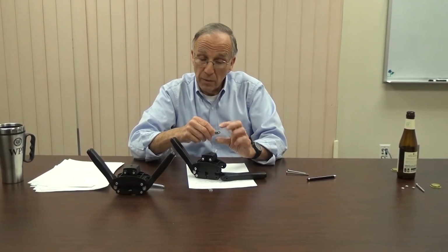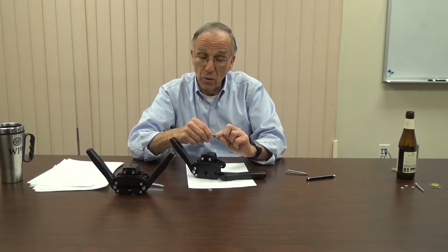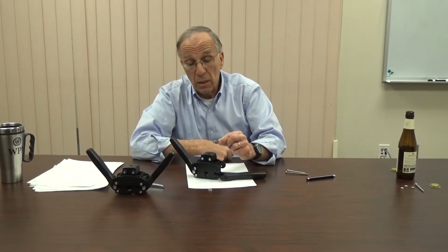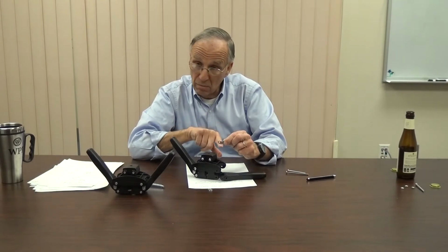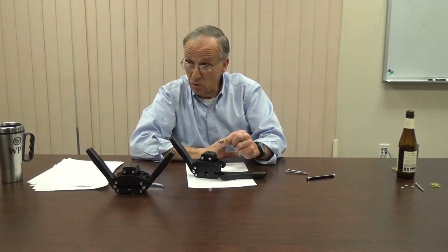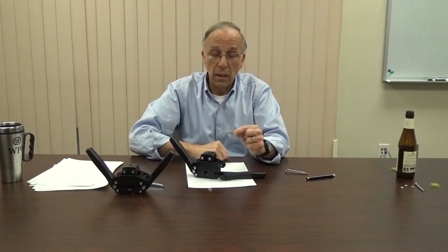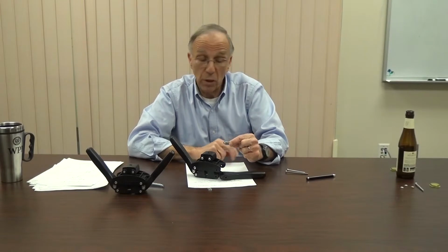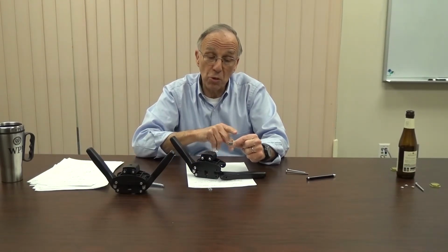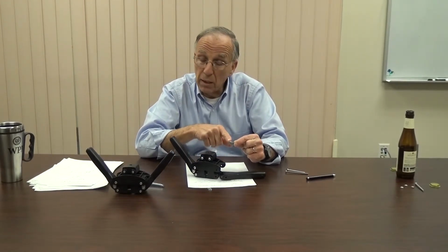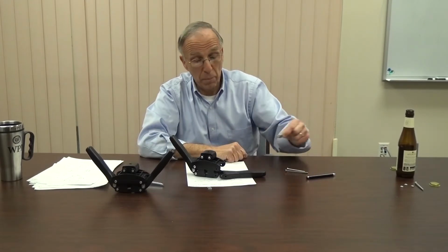Now, of course, this does not have a uniform cross-section, so the stresses vary with position here. And also, if we looked at the stresses on a slant plane, like the first example, we would find we would have normal stresses and shear stresses on a slant plane in this device, even though it's a two-force member.